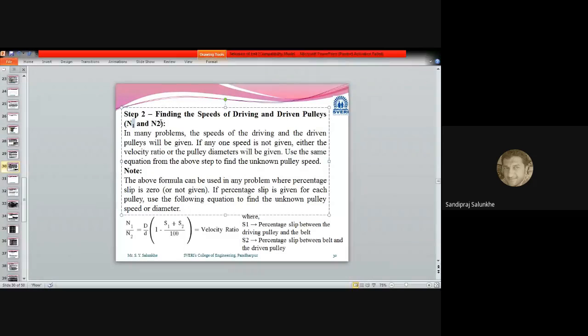But as the first step mentioned, we are not going to take the exact value of the pulley diameters. What we are going to do is select from the available standard values of the diameter. So when we select the pulley from the available data, the value we get will not match the previous value which we knew.